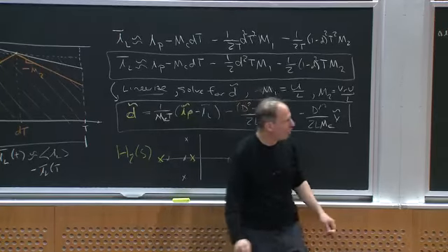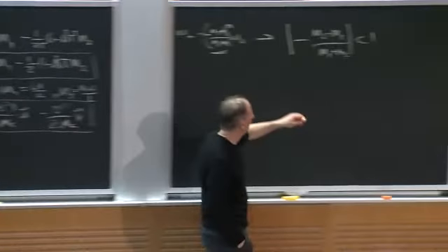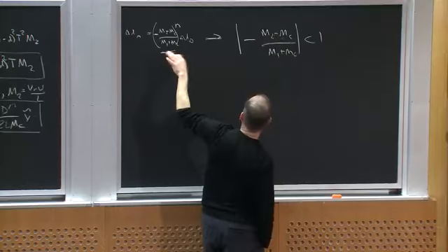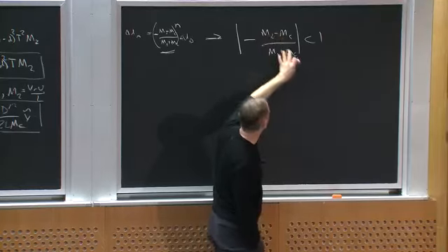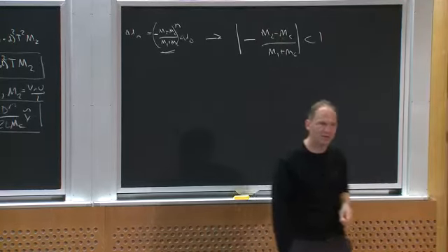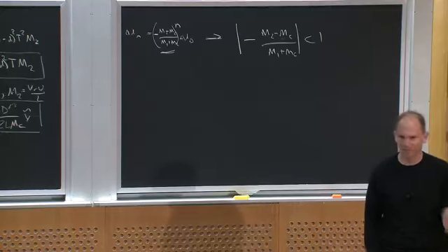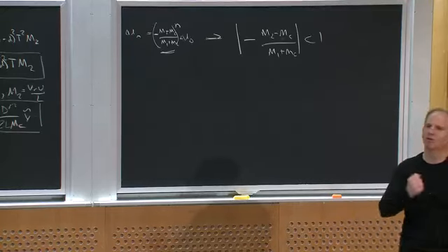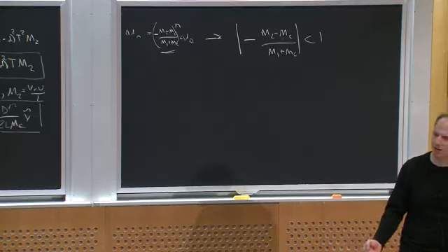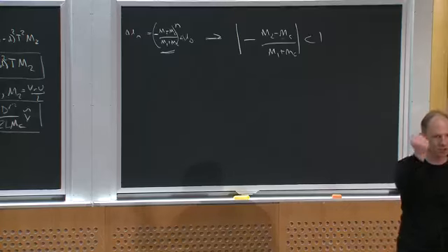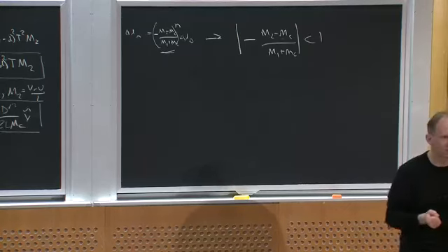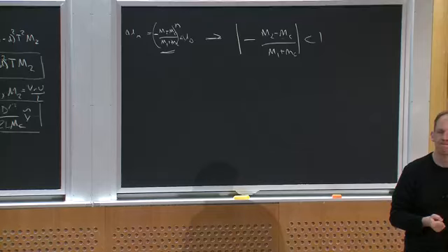Okay? I could also obviously make my compensating ramp slope depend upon M1 or M2 in some way. People don't usually go to that range. If you have your converter operating over a really wide range, maybe you start to play those games. But generally, you're just picking some slope and setting it with a resistor or something. Questions?